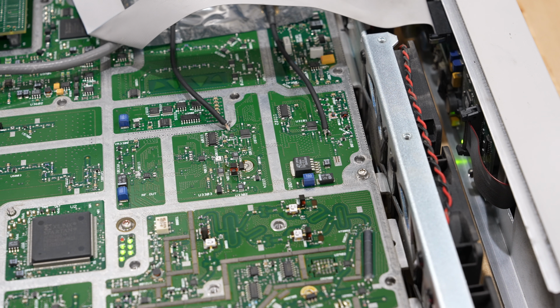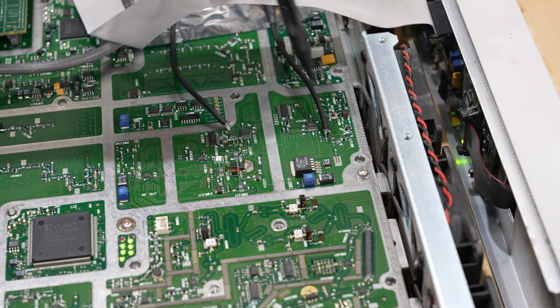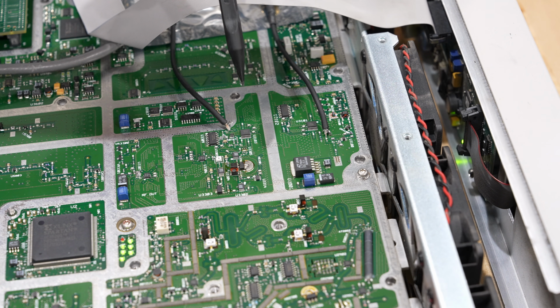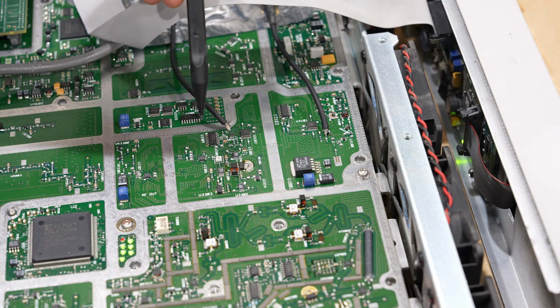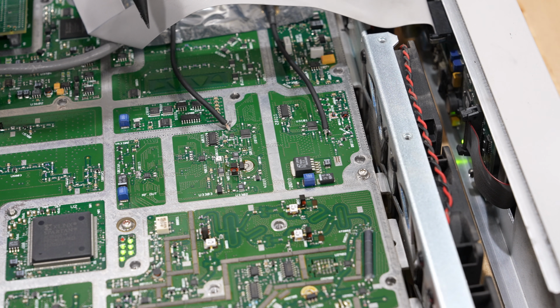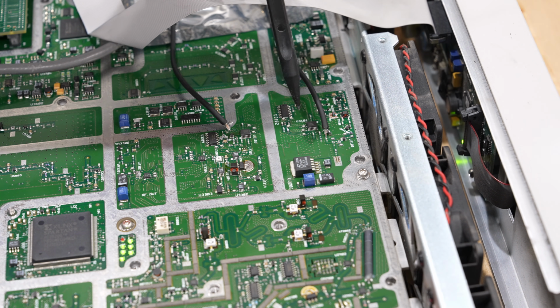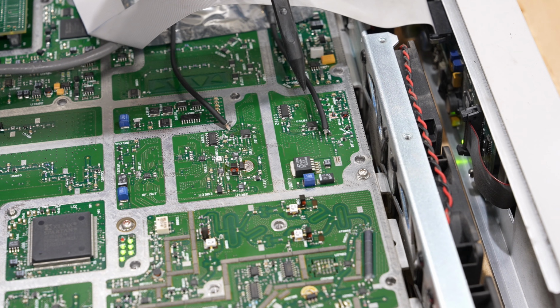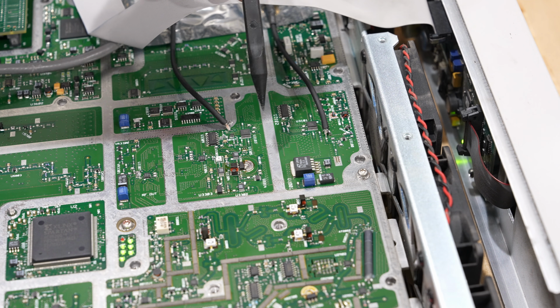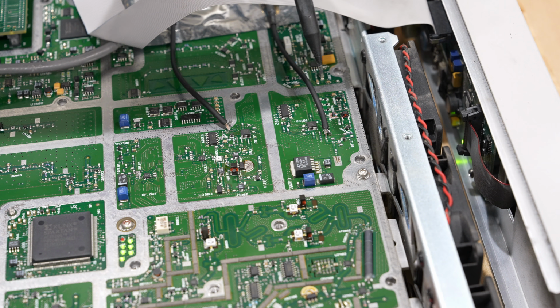And so I've gone ahead and removed 2 of the series capacitors on the board, and I'm using those pads to attach 2 coaxial cables directly in their place. Here's the input of the filter, here's the output of the filter, and the switches and everything, plus the amplifier is now in the path. Now this allows me to also scratch a little bit off the silk screen to connect the ground of this coax. This transition isn't going to be perfect, but it's going to be good enough to see if everything is working.